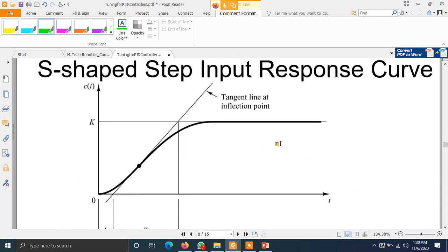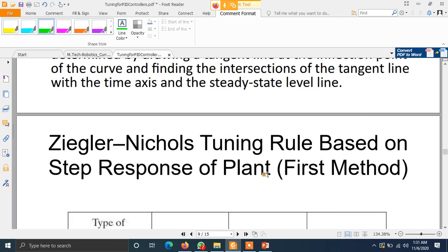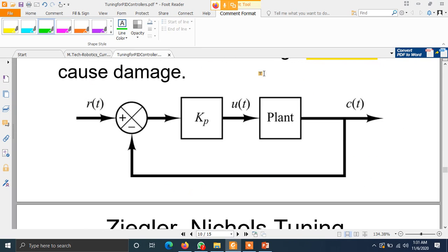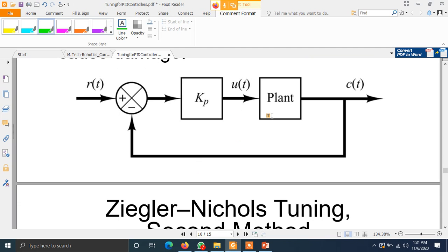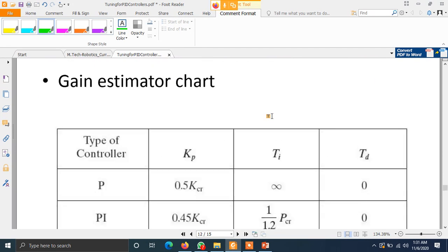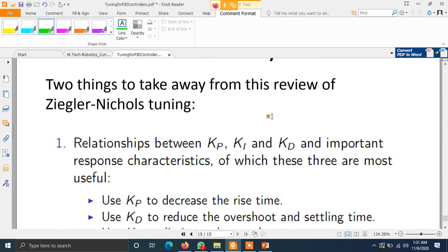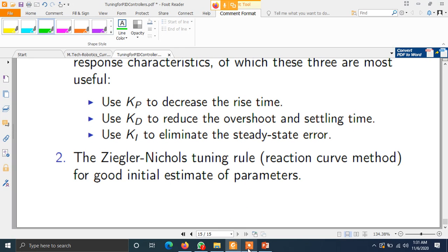you have to give only a step response. But what happens if the system dynamics vary? I cannot give the step response as an input all the time. I have to vary it. At times I would give a ramp input and find out the response, and find out the other parts also. But ultimately, as the complexity increases, you have to go with only this method. But there is a potential cause of damaging the plant if you are not setting the Kp value properly. So in both cases you require some expertise, right? Any other doubts with tuning of the Ziegler-Nichols method?